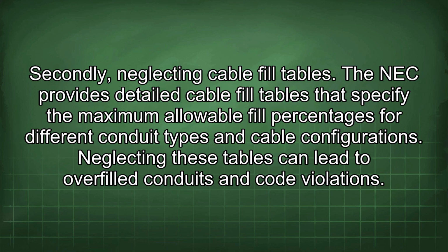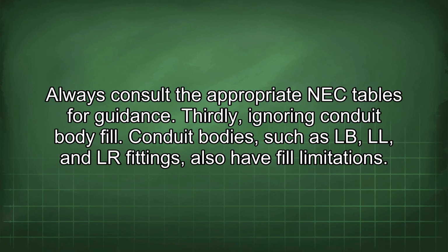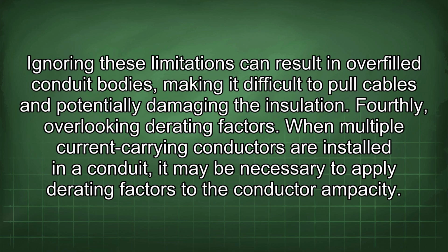Secondly, neglecting cable fill tables. The NEC provides detailed cable fill tables that specify the maximum allowable fill percentages for different conduit types and cable configurations. Neglecting these tables can lead to overfilled conduits and code violations. Always consult the appropriate NEC tables for guidance. Thirdly, ignoring conduit body fill. Conduit bodies, such as LB, LL, and LR fittings, also have fill limitations. Ignoring these limitations can result in overfilled conduit bodies, making it difficult to pull cables and potentially damaging the insulation.